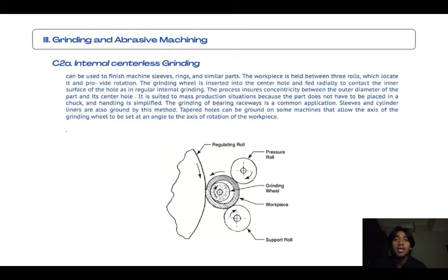These machines are typically used in production applications while horizontal spindle machines are more common in toolroom or jobbing work. Vertical spindle machines are used in the manufacture of cylinder head surfaces, gear and pulley faces, and other parts where flat, smooth surfaces are required.